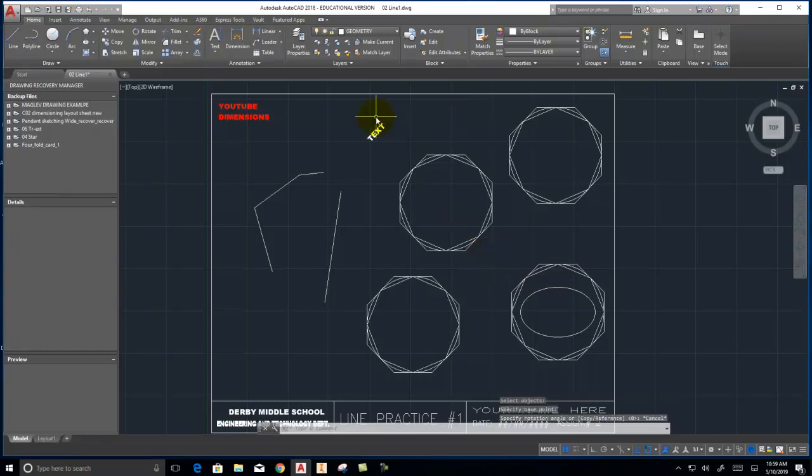Okay? So for this case, I want to select the text, and I want to pick the center of the text. And I want it to be straight now. So you can see that right there, it looks pretty good, but I put it at a 45-degree angle, and I want to change that to -45, or I could take 360 degrees and subtract 45 degrees from that, which would be 315 degrees. And you can see right now that looks right.